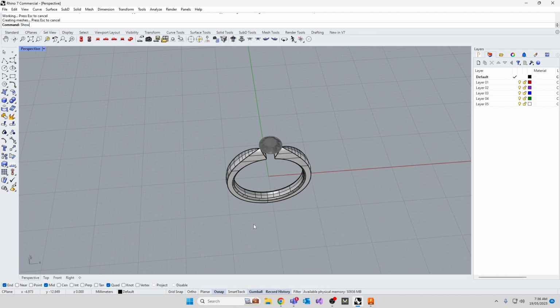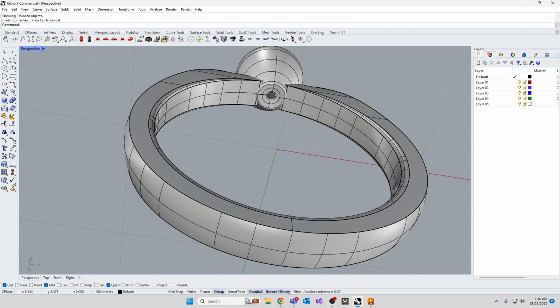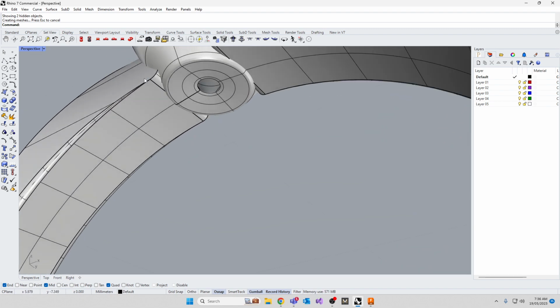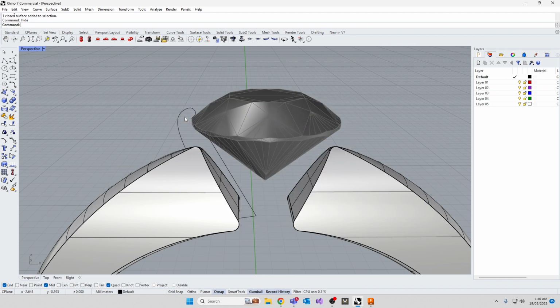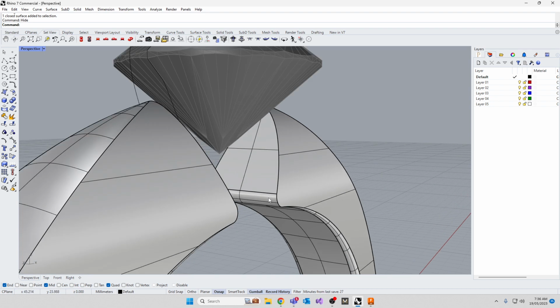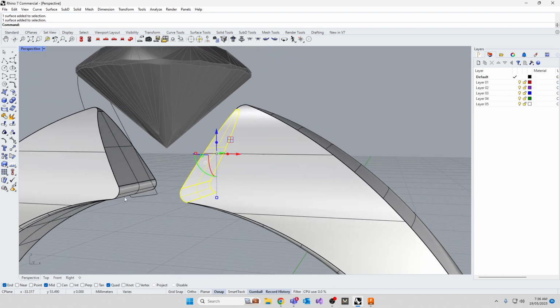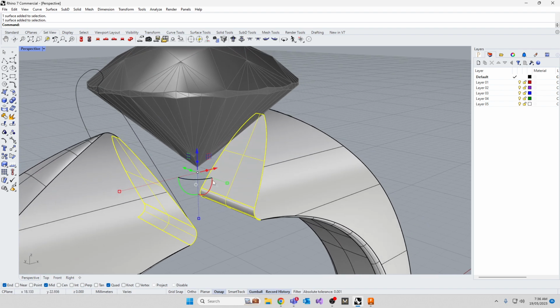So now let's show everything we had out before. So now you got your stone, you got your bezel, you got your shank. Got it. Now the thing that broke for you yesterday. Oh goodness me, I'd really like to not see this over here. I'd like this bottom to have pinched in. So when we did this before, we said, okay, let's hide that again. We said you can try to super select. Sometimes you get away with it, sometimes you won't. You can try to super select this surface here. Control Shift U. Control Shift U. I don't think that's going to work. We can try. And you can try to scale them together.